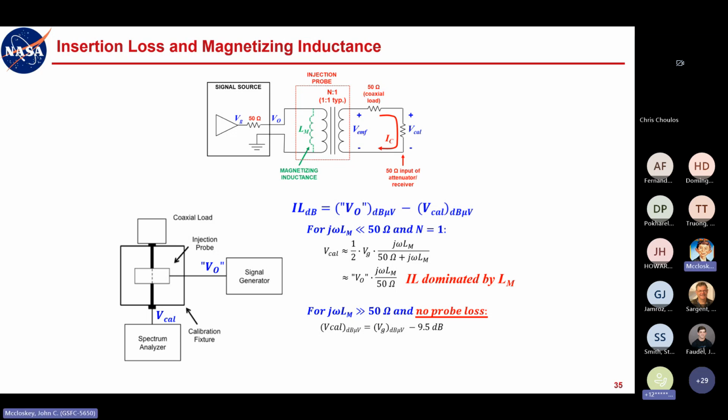Okay, so you have three 50 ohm resistors in series and you're tapping off only one of them. So it's just a simple resistive divider. So 1/3, well, a lot of times we round a factor of 3 up to 10 dB, and in most cases that's close enough for what we do. But 1/3, a factor of 3, is actually about 9.5 dB.